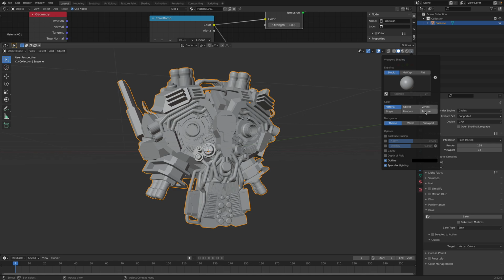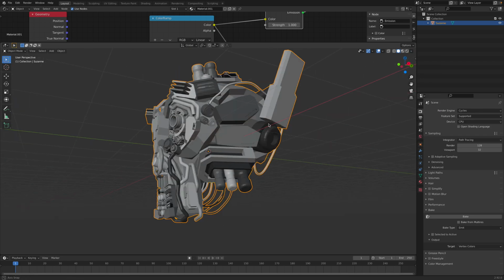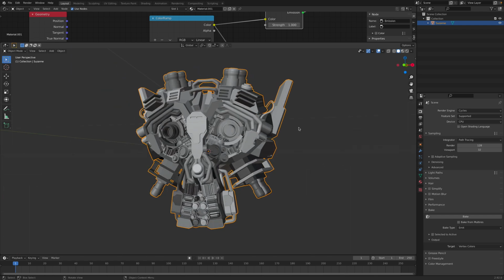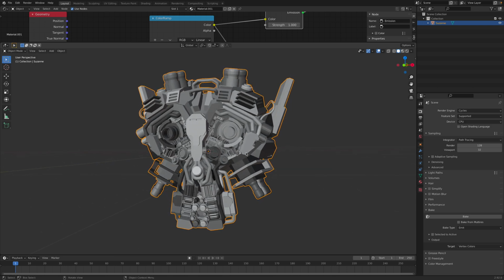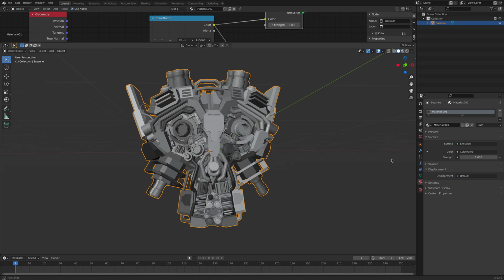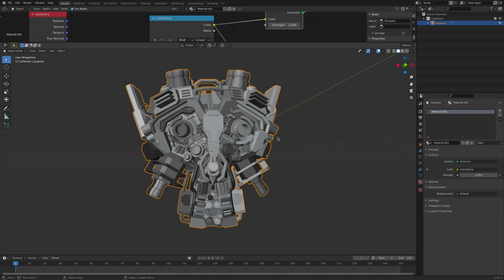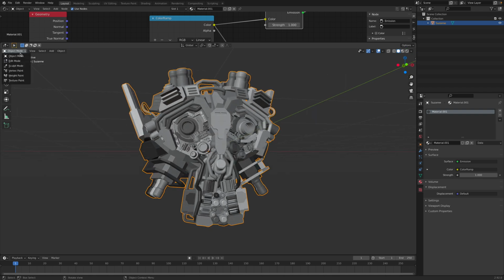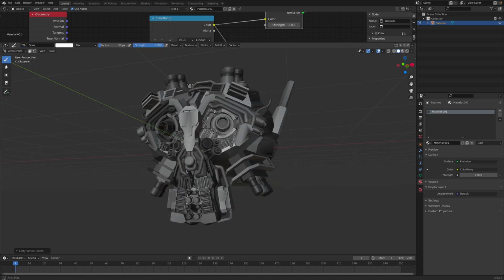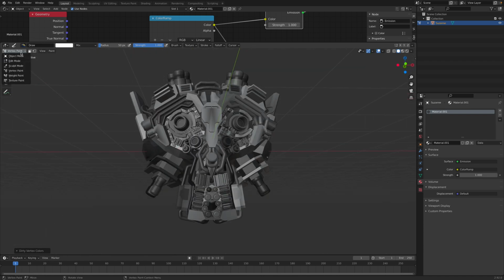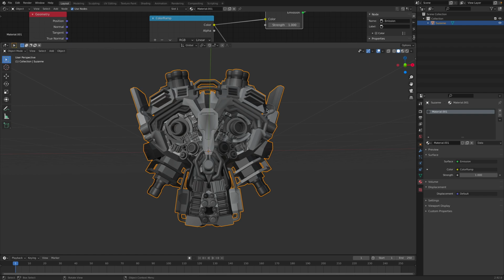If you look at this under the vertex paint, you can see each part has a different color. You can also check it out, you can turn it on here. Different color for each part. That can be useful because we can use a Python script or something like SideFX Houdini to randomize a different material. So we can assign a different material to each object, randomly using the different colors. That could be handy. With Vertex Paint, by the way, you might also know there's this dirty Vertex Color that will add some kind of dirtiness. This is also something that you might want to do, but you can also use PxrRenderMan to do that.